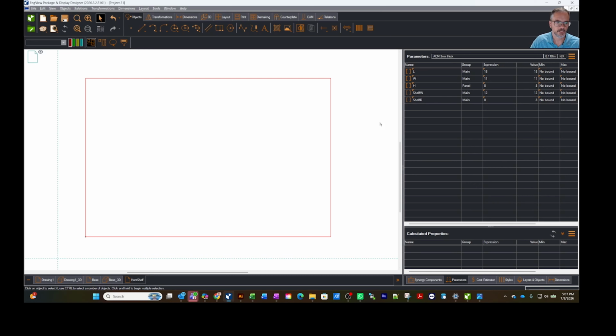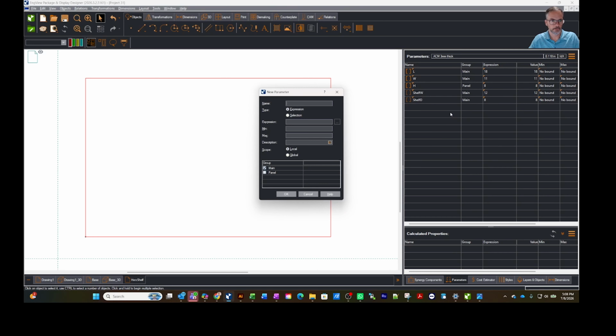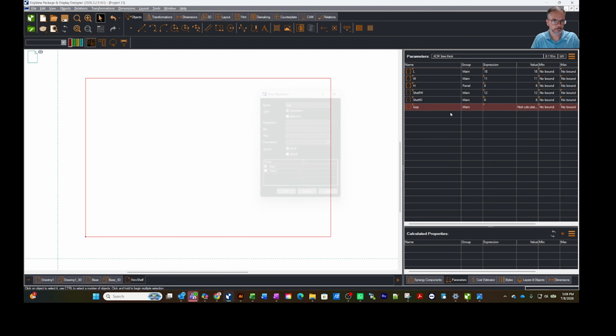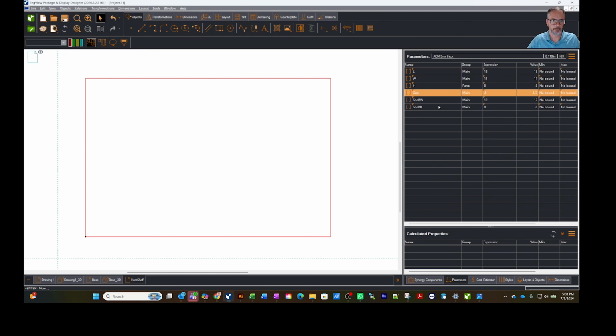And now we can use these values, but we want to take into account because these were the outside dimensions on that. So we'll take our shelf width and, we could add a gap, we could add whatever we want. Maybe it might be kind of fun. So let's do a new parameter and let's call this gap. And let's put in like 0.5 in there. And let's say that we want our shelf width, we'll move gap above here. Let's say we want our shelf width to be our width minus our material thickness minus our gap. Oops, gap. And if I could do that right, gap.